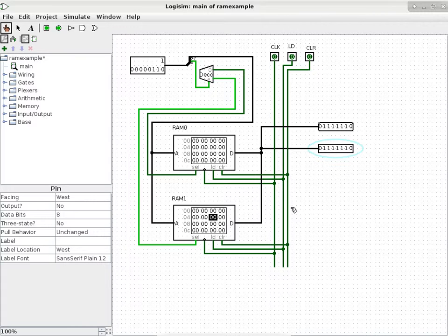Oh, but nothing is happening. Well, nothing is happening at this point because the RAM chip does not change its content. Even if you specify the correct address, the correct data pins, and specify a write operation, it doesn't happen because you need to have a clock transition. Now with this particular one, it specifies that it wants a low to high transition on the clock line.